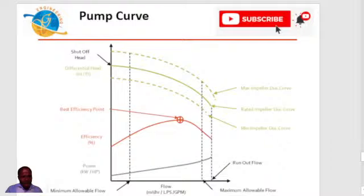So as you move further away from the best efficiency point flow rate for this given curve, you can see the effects on the power requirement. The power requirement is going higher. So meaning that as you run your centrifugal pump further away towards the right, away from the best efficiency point flow rate, the power requirement to drive that pump is going higher. So the power consumption increases with increase in pump flow.